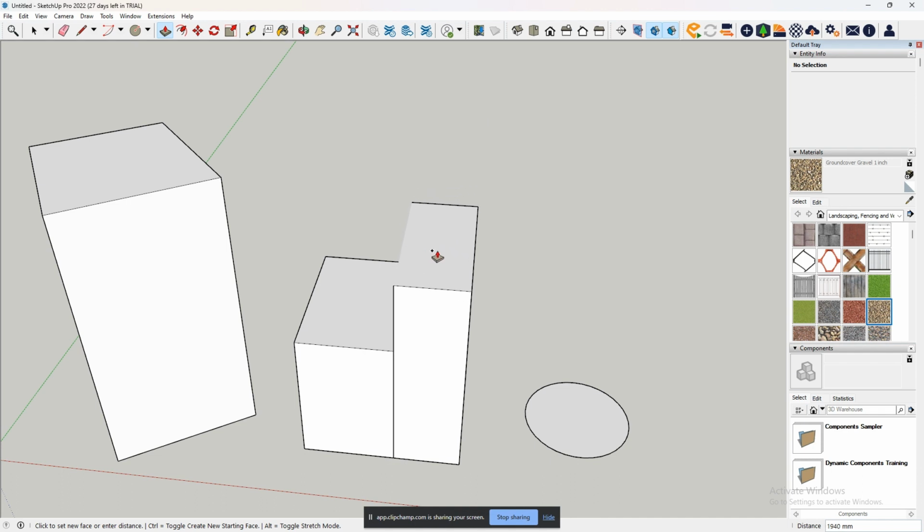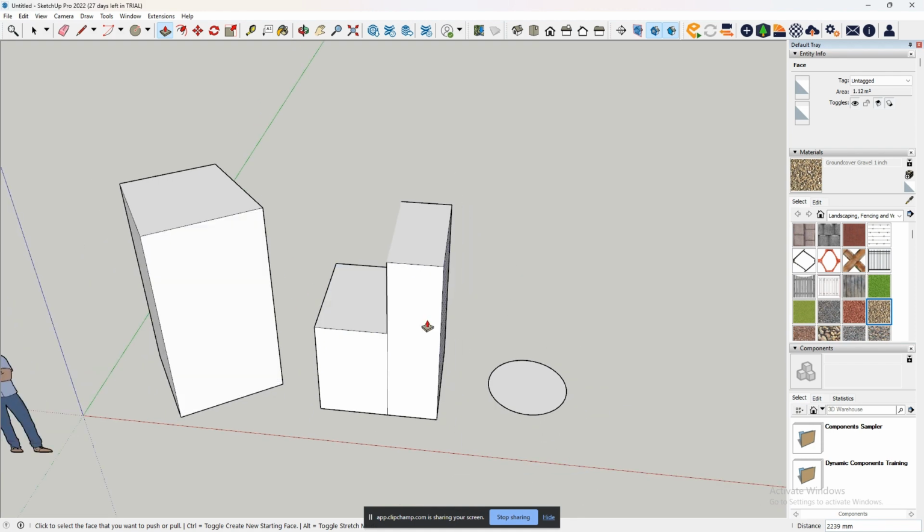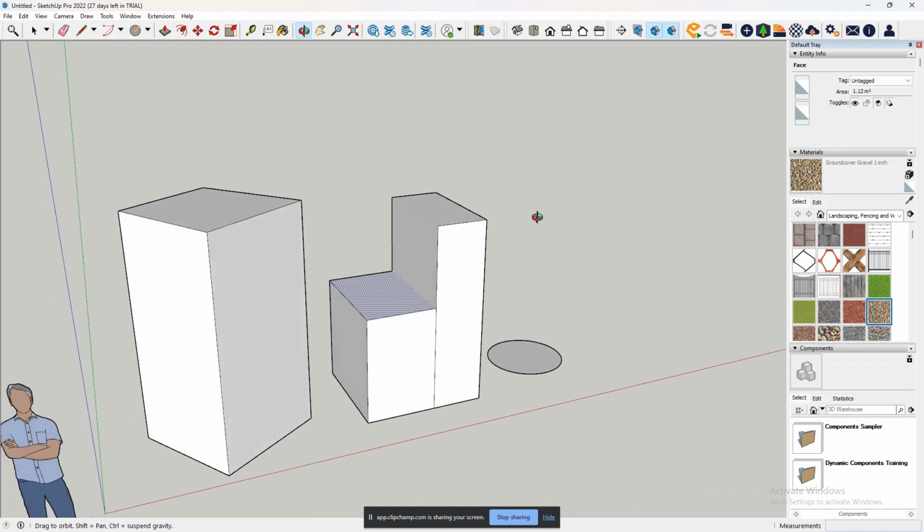That is a very common annoyance in SketchUp, getting stuck on that offset, but pressing that Control allows you to continue going. I would recommend though hitting the Control again to get rid of it, because if you keep that plus sign next to the push-pull, it can cause some issues later down the track.